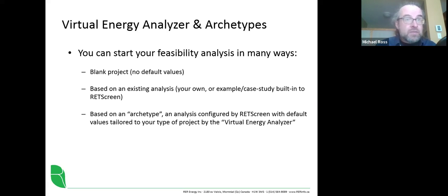You can start a feasibility study or a feasibility analysis in RETScreen in a number of different ways. For instance, you can start with a blank project with no default values in your project. And that's how I'm going to start the first study today. You can also base your analysis on an existing analysis. So that could be a project you've already done and you've saved, so you just load it and change values. Or it could be an example or a case study that's built into RETScreen.